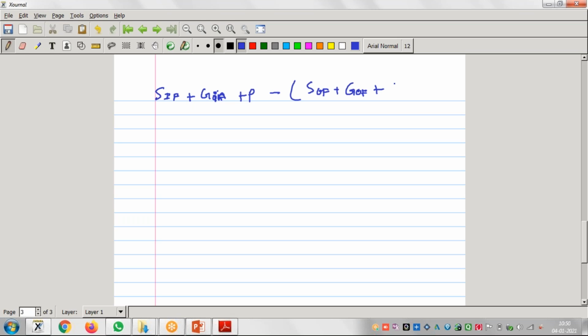This is inflow, right? This is outflow, plus evaporation loss is equal to change in storage, right? So change in storage is minus because the incoming quantity is less and outgoing quantity is more. So that's why I'm taking it as a minus. And it is given as 16 million meter cube.